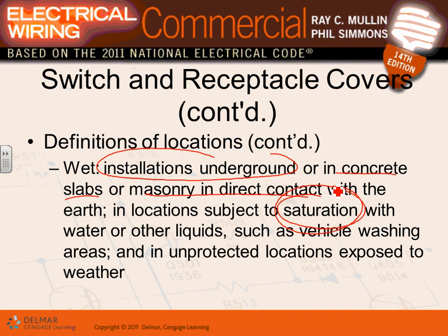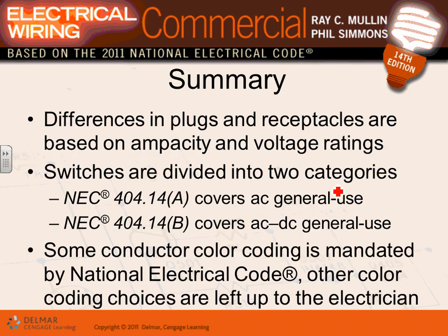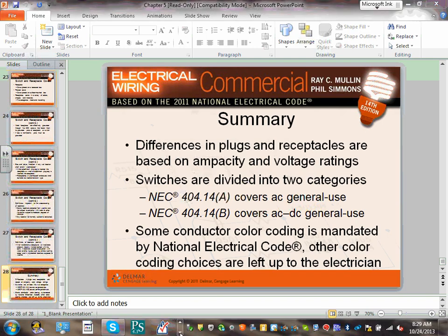When we put a conductor there, guys, it has to be rated for wet location. When we put equipment there, it has to be weather resistant, in use cover, and enclosure rated for that location. Does that make sense? Fixtures, receptacles, you name it. So these are the most important things about the wet location. Let me show you a couple of pictures here, and then I'll switch into CAD.